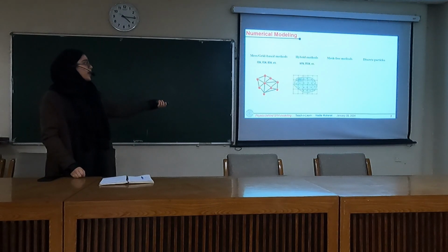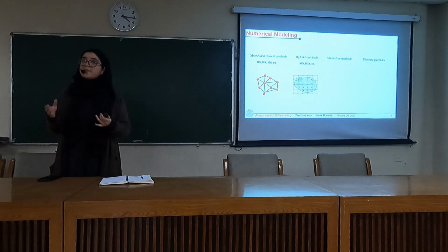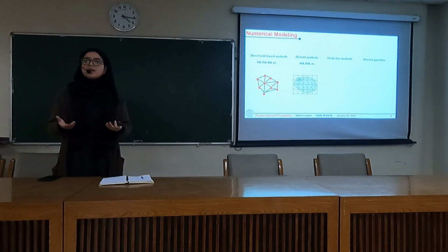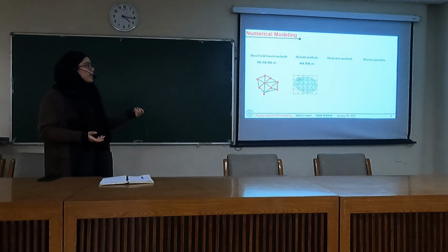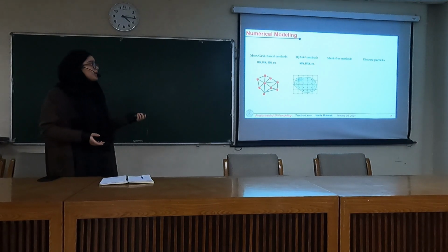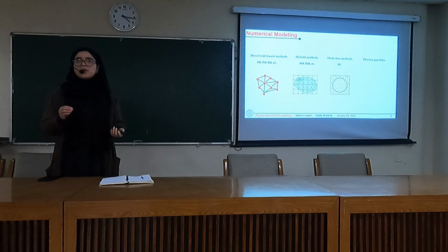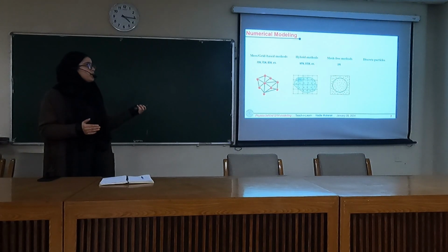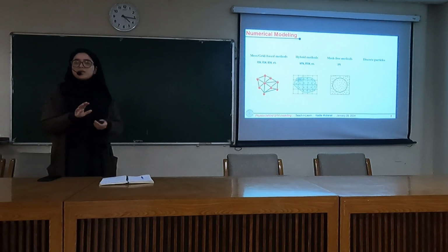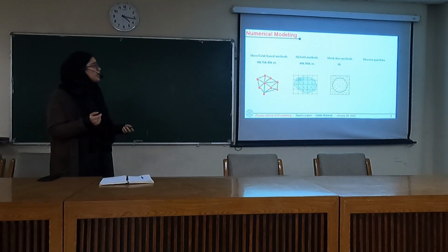Then we have hybrid methods like the material point method or particle finite element methods, where we have a background mesh as well as particles. So if we need to calculate some properties like mass, velocity, etc., they are calculated at these particle points, the material points, and then they are extrapolated onto the background mesh. And talking about mesh-free methods, there is only one truly mesh-free method. Some people call these methods mesh-less methods as well, but if there is one truly mesh-free method, that is SPH, so there is no background mesh, the domain is discretized into particles, and then things are carried out.